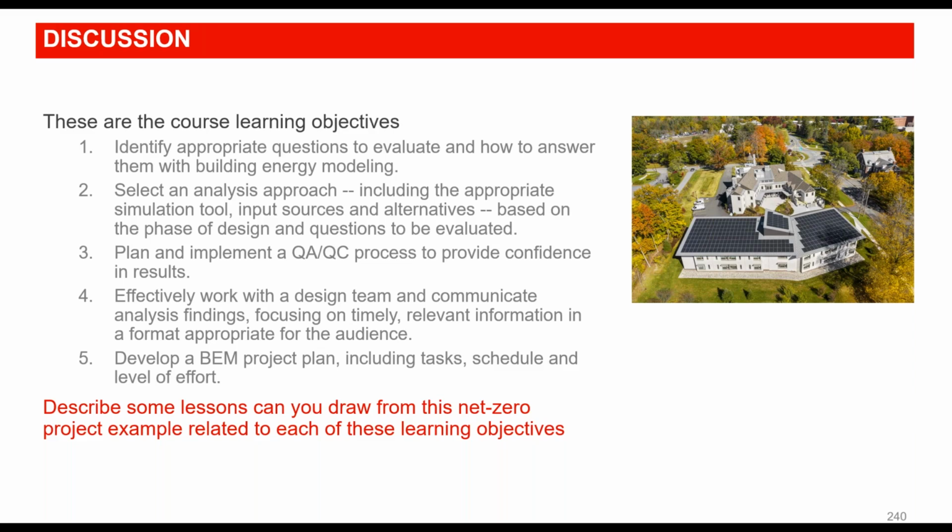Mark asks, do any of the packages you cover include hydrothermal modeling? And Mark, no, this is really just an introduction to building energy modeling. We don't cover some of that detail. As you said before, WUFI is a great tool for that, and I know there's training available for that as well. ASHRAE also has Standard 160, which deals with hydrothermal modeling, particularly from the weather data standpoint.